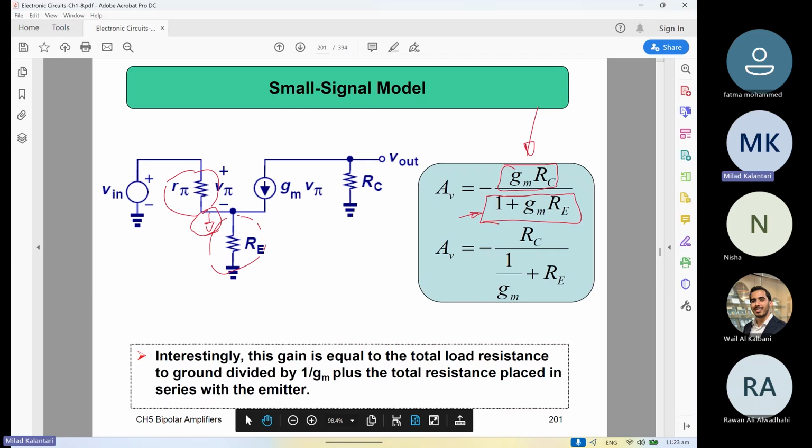The impedance from the emitter side was 1 over beta times less, right? Because the current was beta times higher. Do you remember this? Comparing to the base, the current is low, so the impedances are big. At the emitter, the impedances are low because the currents are higher. The ratio between the base and emitter is 1 plus beta, or so, right?